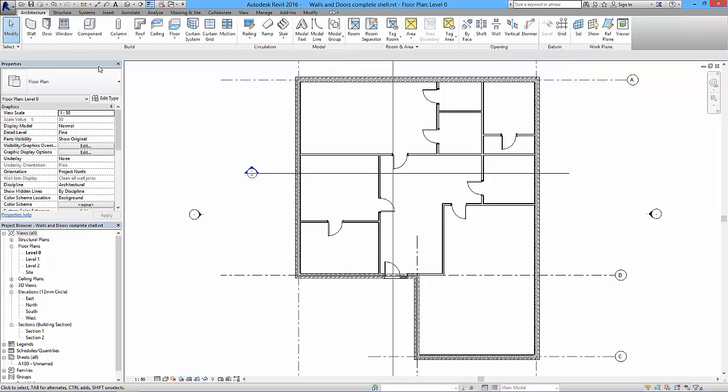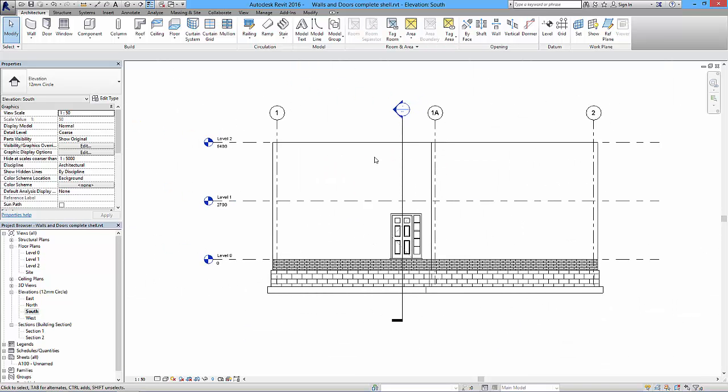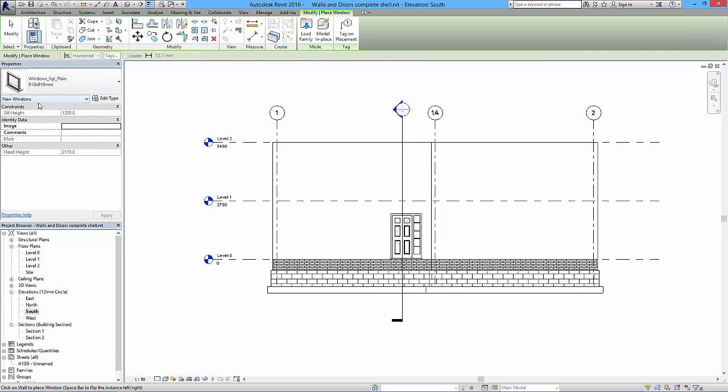The only thing about a window, when you bring it in, we'll go back to our south elevation because we've cleared the cladding pattern in this south elevation. If I choose a window, we've got a sill height that is set for the moment. The head height and the sill height are set. And when I bring it in to an elevation, when it reaches that sort of 1200 sill height, it's going to throw out that little blue line. Okay, and again, position these things.